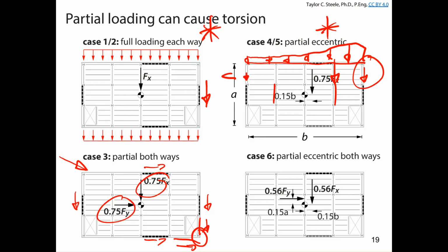Statics are different depending on where your brace frames are. That determines what your reaction forces are going to be. You just have a different statics problem to solve. This might result in a larger force there than that one would. Any questions about that concept?